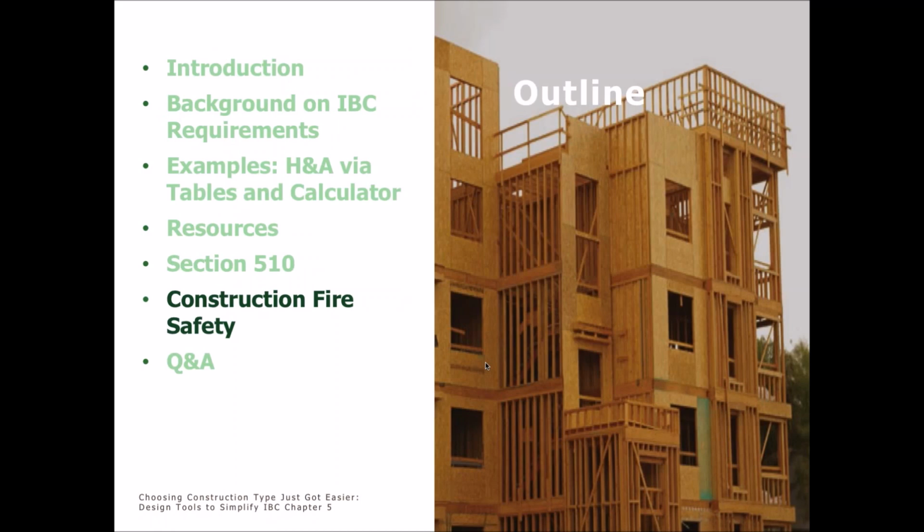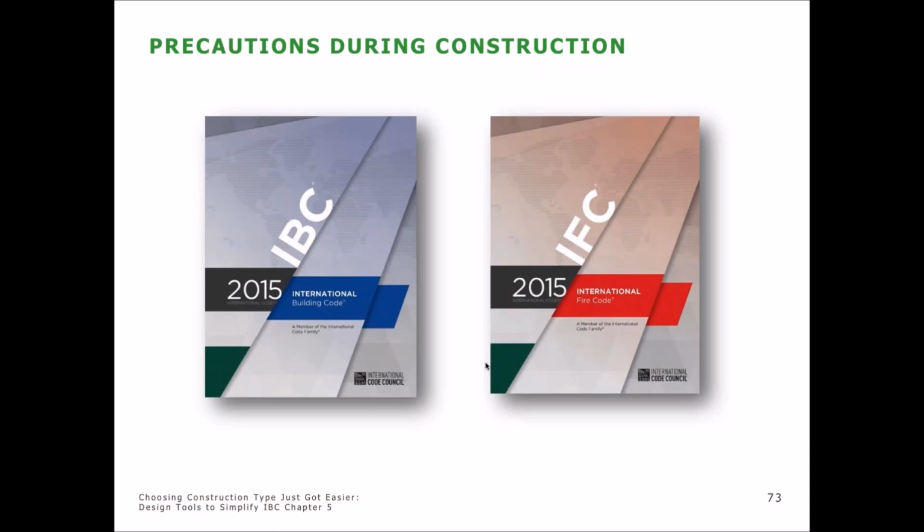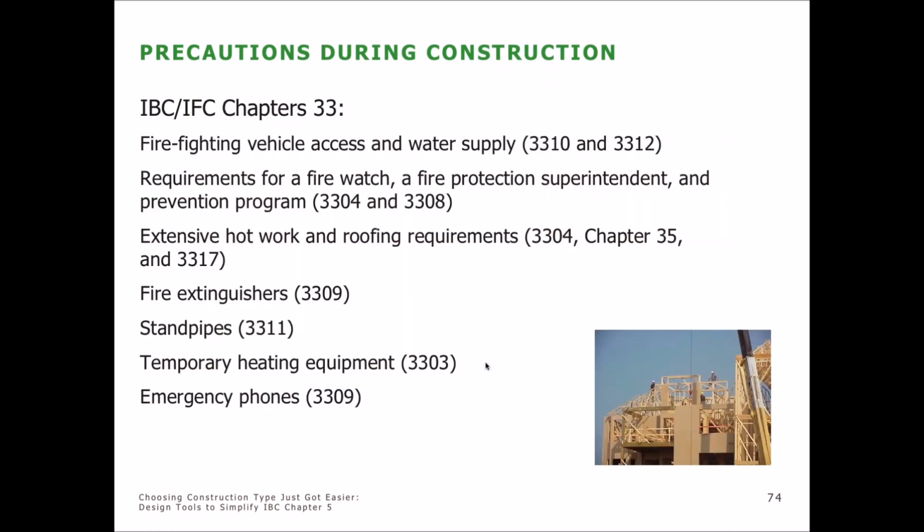Real briefly then, just to wrap up before we leave some time for Q&A, we wanted to at least provide a few resources available to you on the topic of construction fire safety. The first is to point out that chapters 33 of both the IBC and the IFC provide provisions relative to enforcement of applications specific to construction fire safety. To give you an idea of what some of those provisions are, it's looking at things like hot work, placement of fire extinguishers, and fire watch provisions, which are a big item to keep in mind there.